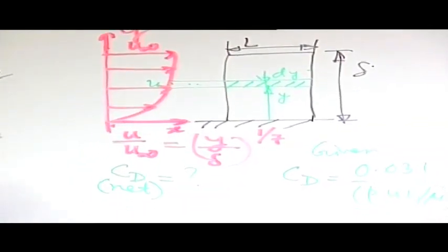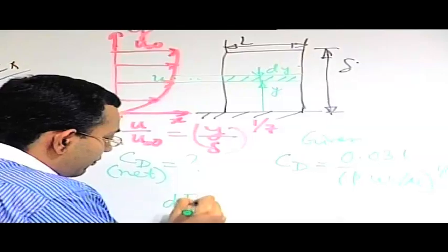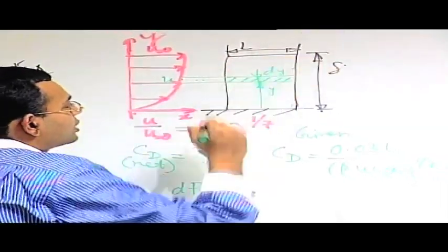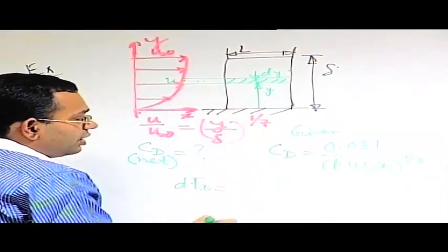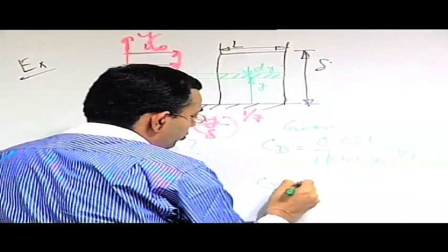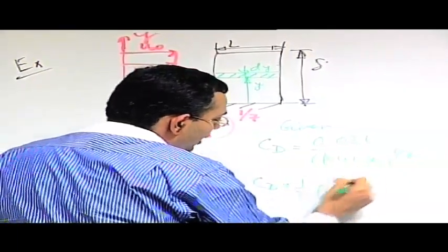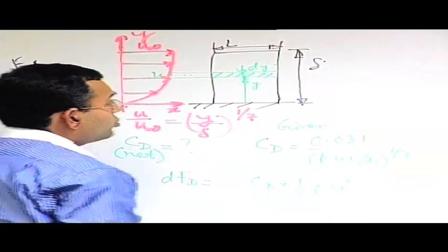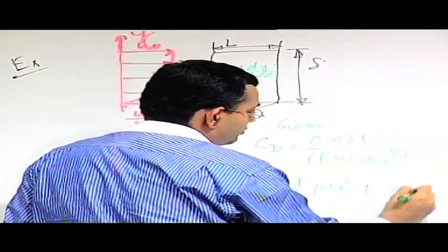So then if you calculate the local drag force, the local drag force is the local CD into half rho local u square into the area L dy.